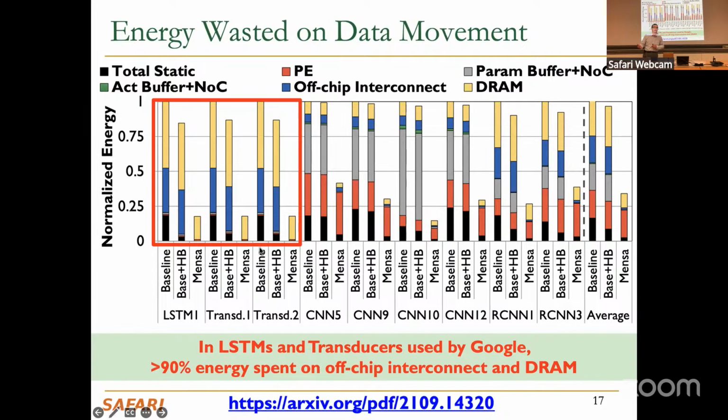And as you accelerate computation, whenever you design an accelerator, usually the acceleration of computation makes memory a bigger bottleneck, right? Because you accelerated computation, computation is much cheaper in terms of time. Amdahl's law says that whatever it is that you didn't accelerate becomes a bigger bottleneck because it's occupying a bigger fraction of the time, right? And you all know Amdahl's law, hopefully.